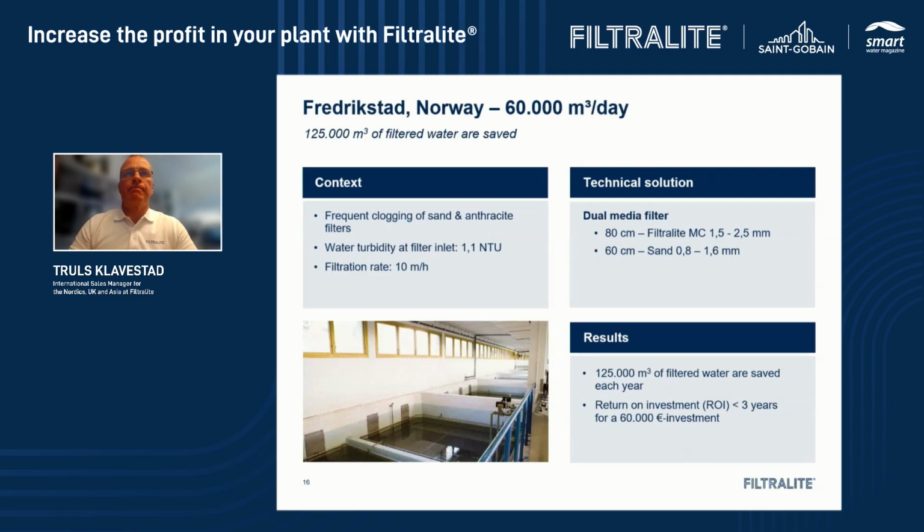And then this is a plant very close to where I'm living. This case is quite old, but they had a big problem with clogging of the sand and anthracite filter. They have something we call mud balls as well, which can happen due to the chemical dosing and the particles in the raw water.